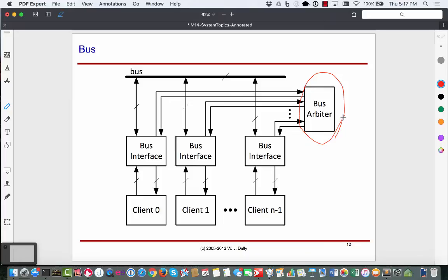Every round, you can think of a round as a bunch of clock cycles, every so often, we'll go to the arbiter and say, hey, I have some data to send. I need the bus. And other clients are doing the same thing. The arbiter will select a winner, and then I get to use the bus for a certain duration, and I will squirt out the data to the other party I want to talk to during those clock ticks, and then we back off.